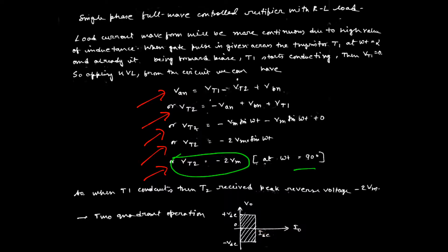So in this operation, we can say the total power is delivered from load to supply, which means the power is fed back from load to supply. That is why, during RL operation, any rectifier that can cover the two-mode operation is taken from the first quadrant operation as well as the fourth quadrant operation.